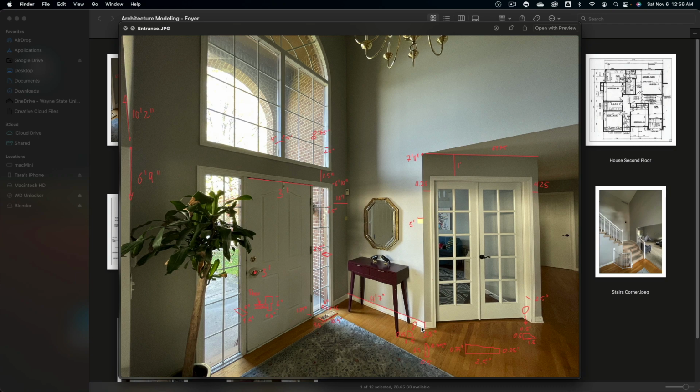Feet will smack against it, and can easily damage the drywall. So besides the baseboard looking nice, the main function really there is protection. Then in this case here, the quarter round that goes around it, that's actually covering up the gap between the hardwood floor and the baseboard.